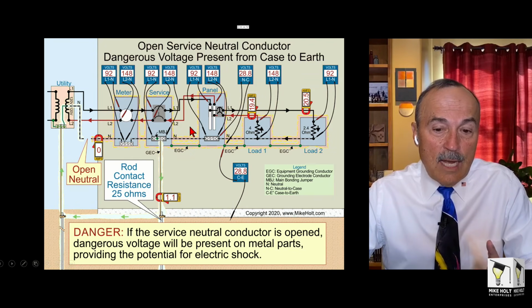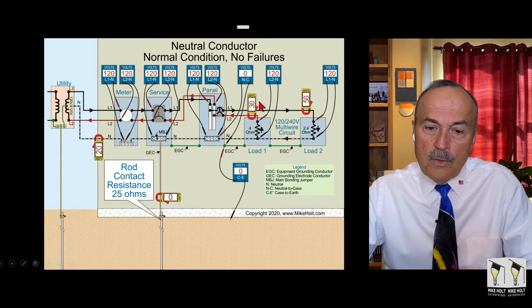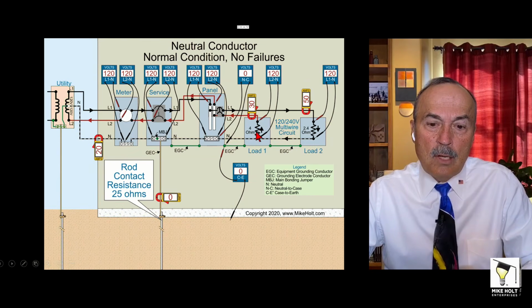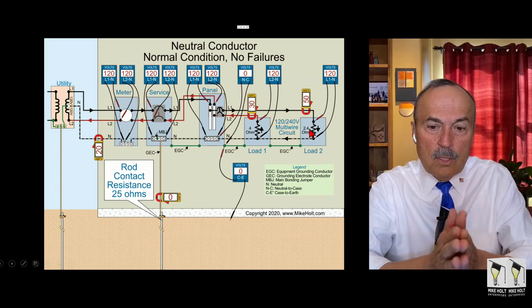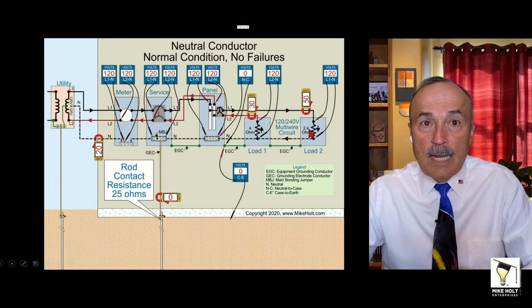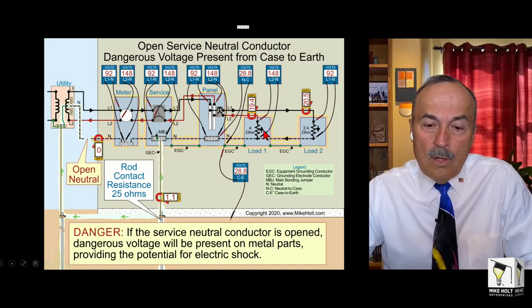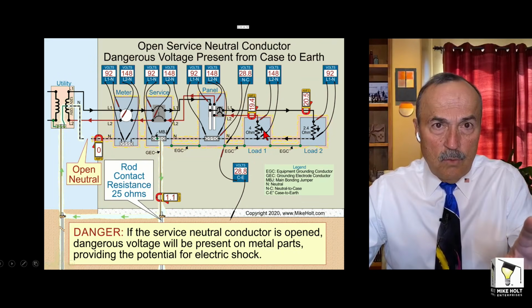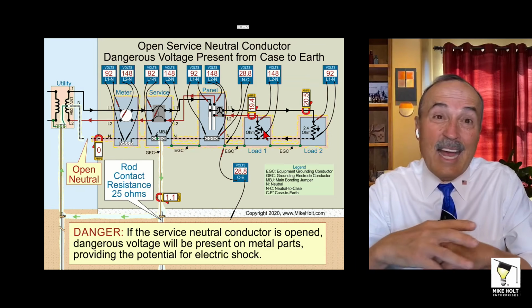As soon as they do that, this load was a 30 amp load and this was a 50 amp load. The actual resistance of the load is 4 ohms, and we can do the calculation of the combined resistance of all those loads. Using that same scenario, but the neutral gets open. Well now, I have a spreadsheet. If you want that spreadsheet, I can send it to you, because this is not something you can do mathematically. I couldn't figure it out.